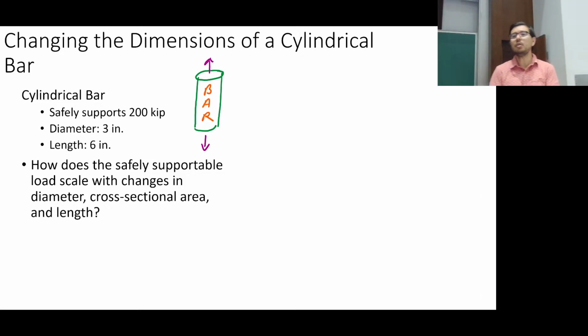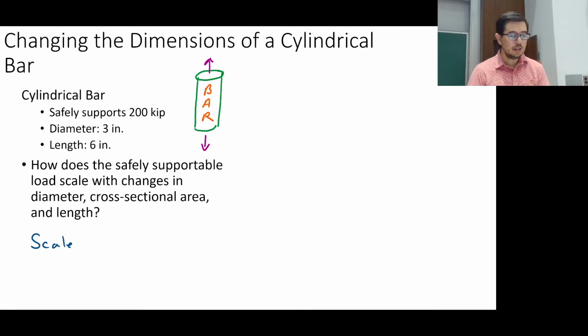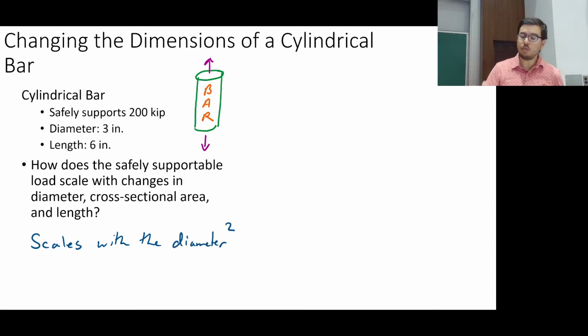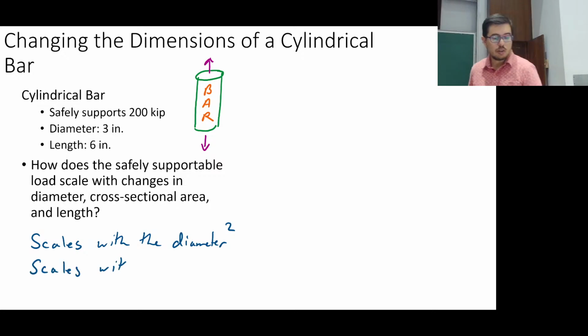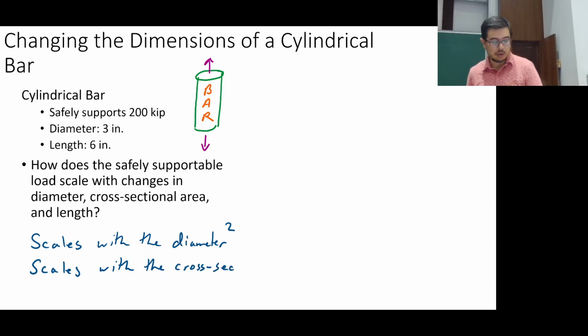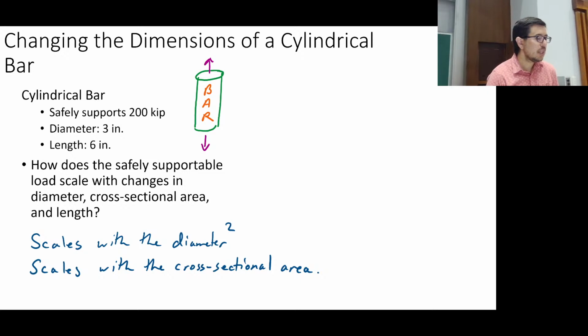So diameter is related to area, okay? And we can say that it's going to scale with the diameter squared, right? Pi r squared, or pi over 4 d squared. And we're going to say it scales with the area. Okay. And what about length?